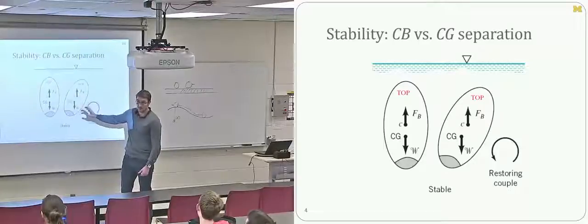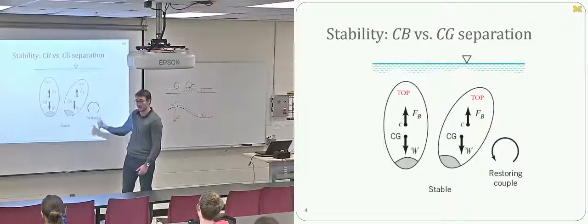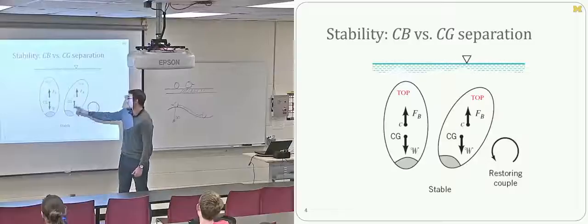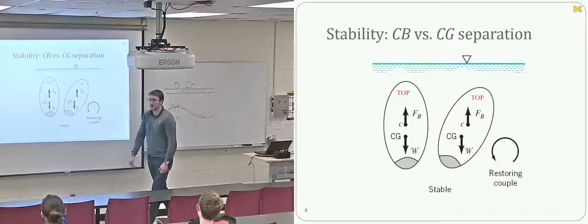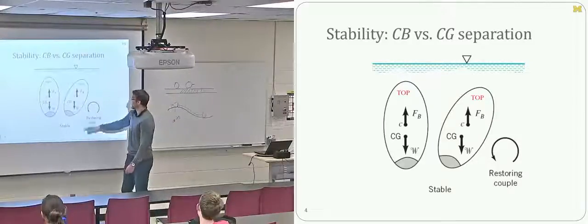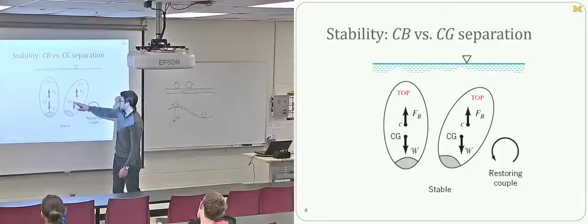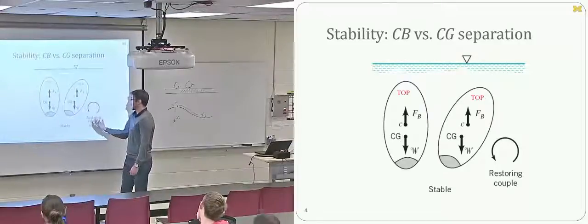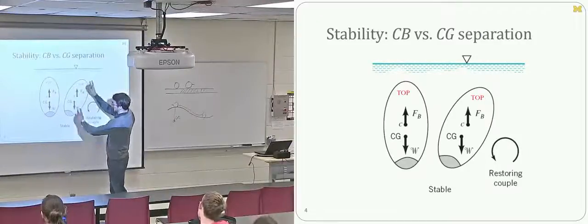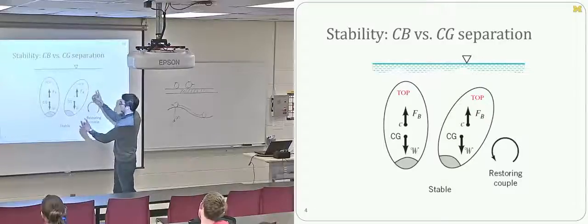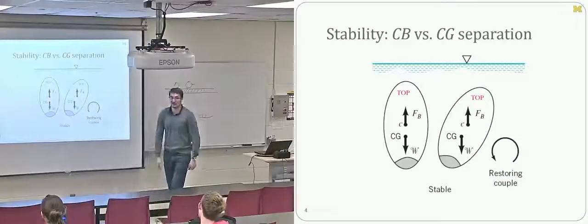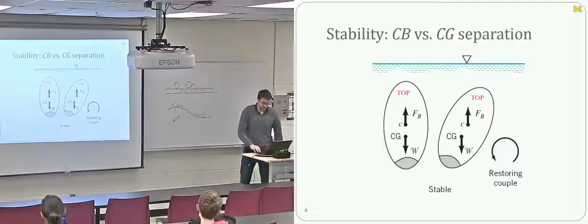It's not dependent on its orientation, it just follows the body's orientation, and buoyancy always acts upward. Same with center of gravity, you're not changing the mass distribution whatsoever. And so what you end up with is a positive restoring moment, or a couple, where you've got buoyancy pulling up, weight pulling down, and they act to correct it back to its initial condition of roll.